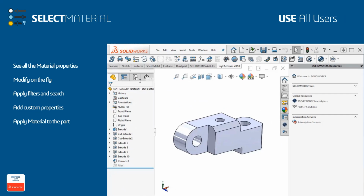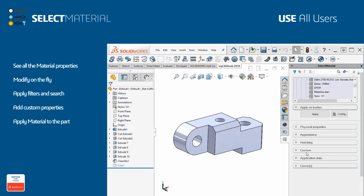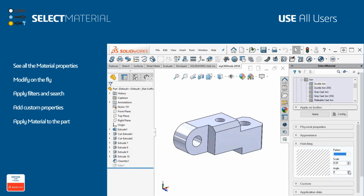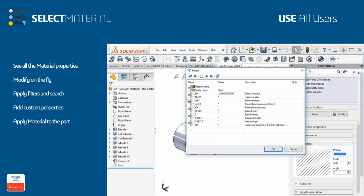Next up is Select Material. Select Material can be used by all users and allows for quick searching of materials within the SOLIDWORKS database. When you select one of the materials, you can see all of its properties. You can then modify them if you want to. Here we can edit the cross-hatching. We can apply filters to help us search for the appropriate material.